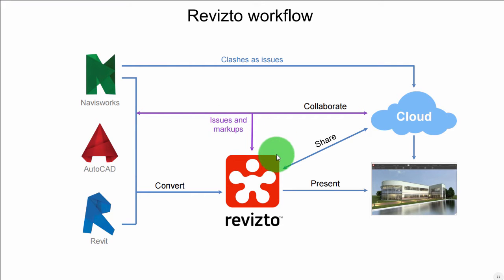If we do the same in Revizto, it's going to be done in real time, pushed out back into the Revit model because we're working on shared coordinates. Any issue you create in Revit is going to show up in Revizto in a 2D and 3D view. And any issue you create in Revit is going to be able to be opened back in anybody else's Revit model that is linked to the file. So we're going to show you that again in a live demonstration here.